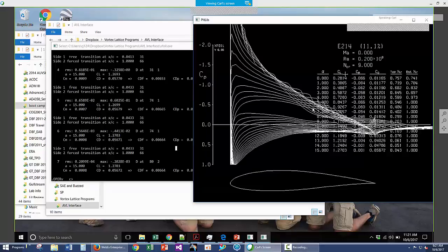And things like, if I'm going to fly at a CL of 0.5, then it'd be about 2 degrees angle of attack, and I can look at what my drag is there. I can look at an L over D, for instance, or just a drag directly and try and pick an airfoil that maximizes that aerodynamic efficiency. So this is not a 1D selection for airfoil. There's multiple things that you have to balance.